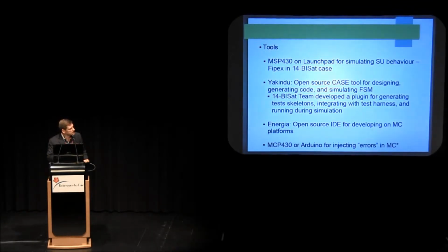We use Yakindu, which is an open source CASE tool for designing, generating code, and simulating state machines. And we also developed a plugin for generating test skeletons. We use Energia, which is an open source IDE for developing on microcontroller platforms, and MSP 430 or Arduino for injecting errors.